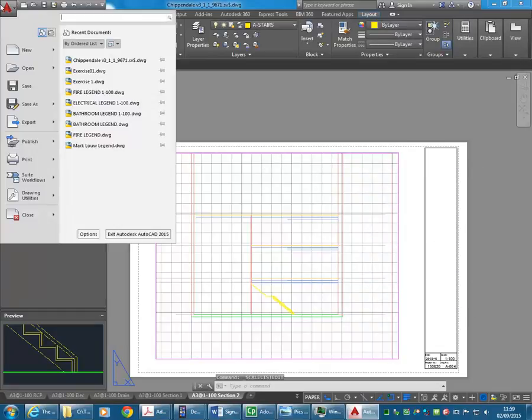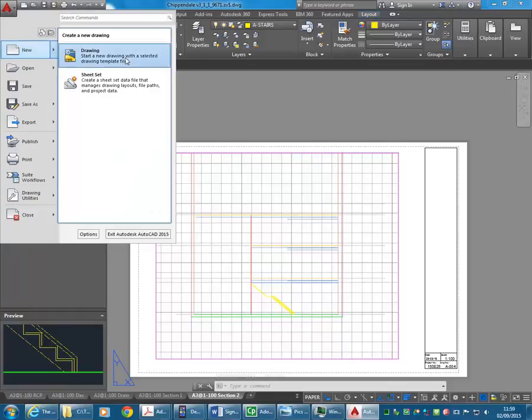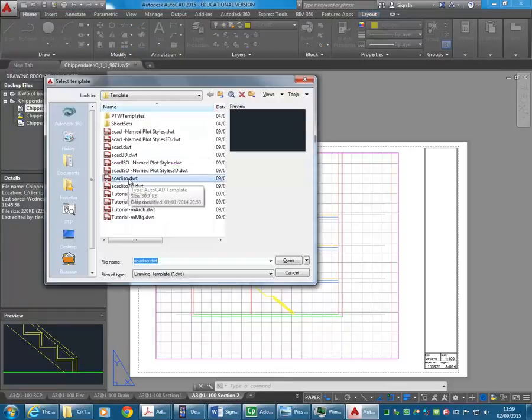So, yeah, if you go and make a new file, you've got to make sure it's AutoCAD ISO. If you use AutoCAD, that's set for metric and imperial. Then some of these others are just set for imperial. Now, the ones set for metric and imperial might sound okay, but they're honestly set more for imperial. It's an American program. They obviously don't work with metric. Simply open your metric ISO and just copy all the scales. That's the best way. Copy and paste it into the right template. It's so much better using AutoCAD ISO for metric.